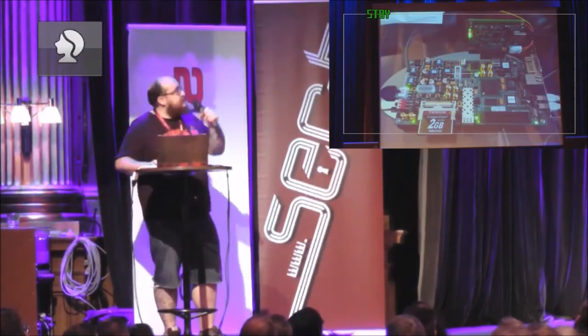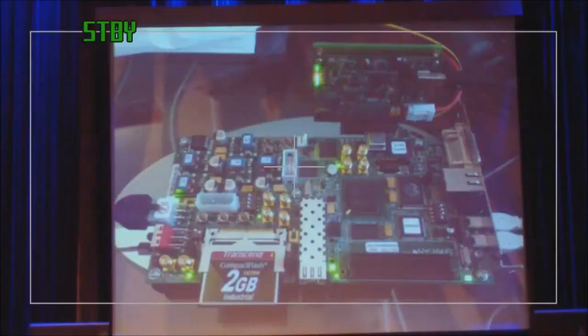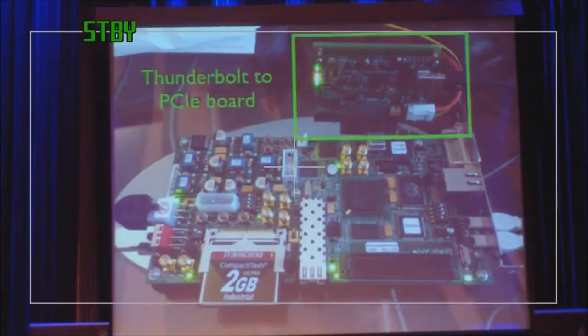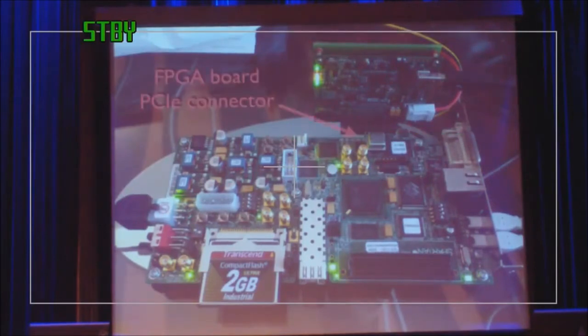So this is our demo, this is our board that we use for this proof of concept. That's the FPGA development board there. There's the FPGA, that nasty looking BGA package there. And there's the Thunderbolt to PCI Express board, that B plus TH05. I bought this a long time ago, and now there's lots of Thunderbolt enclosures that you can buy from Magma and from Sonnet and whatever, that just have a PCI Express slot in a big enclosure with a power supply, basically for having external graphics cards or video capture cards that you plug into your laptop if you're a video professional. So there's the PCIe finger in the 1x slot there, then that's the Thunderbolt connector with the black Thunderbolt cable plugged into it.